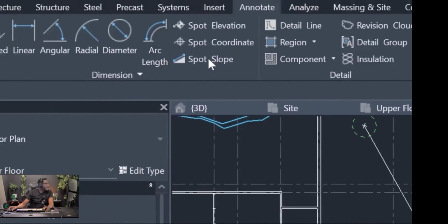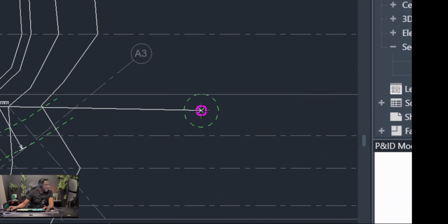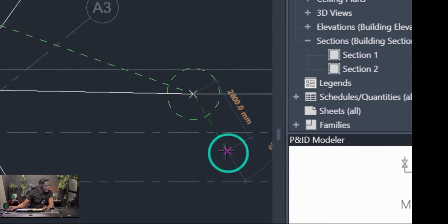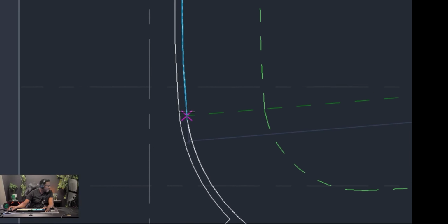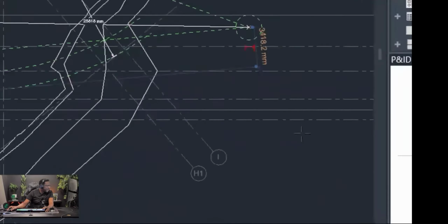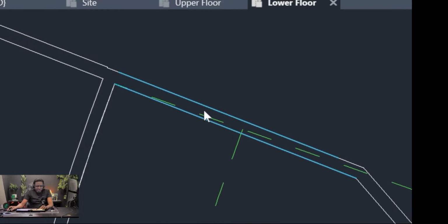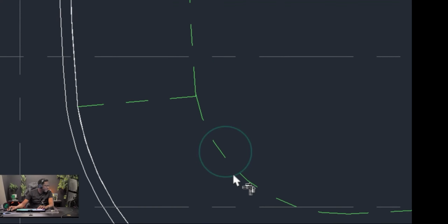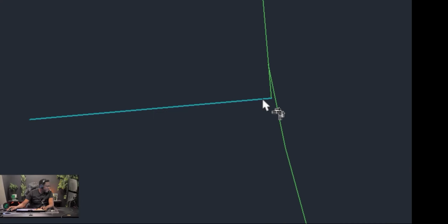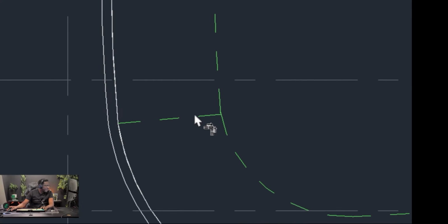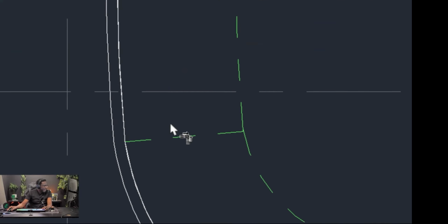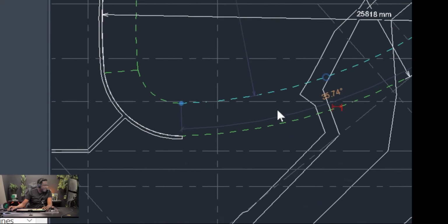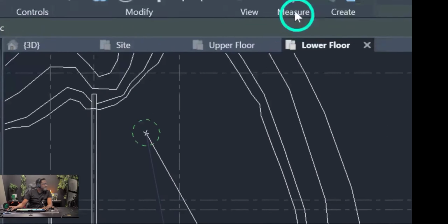So there we go. So now what we can do is when we go to detail line, the line here, I can draw a line from here all the way to the final point here. And same thing again from here to the final point here. Then what I would do is trim this like that and trim this like that. So by right, this is how this should end, like that. Because these threads are on a curve, so it has to be based on a common center point. If it's not, then it's not going to give you an accurate calculation when you're doing the threads. So the same thing for here as well.